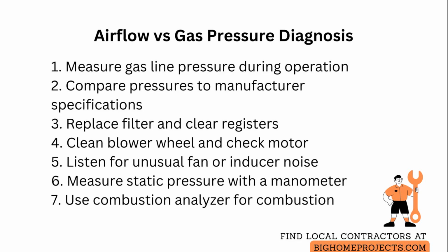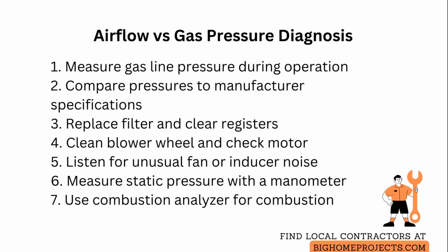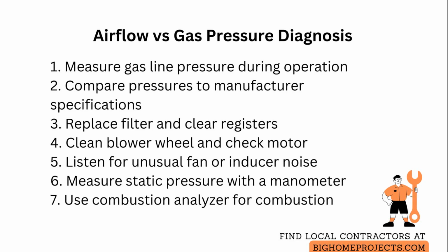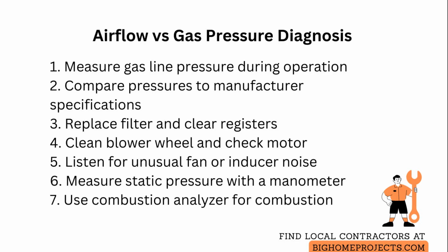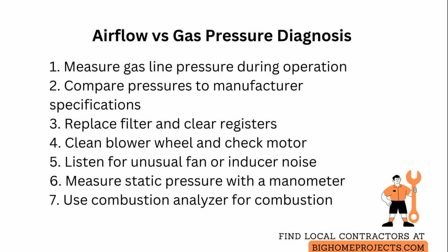Third, listen to the blower and inducer for unusual bearing noise or flutter, which indicates reduced volume. And verify static pressure across the coil or heat exchanger if you have a manometer. High static suggests duct restrictions or closed dampers.